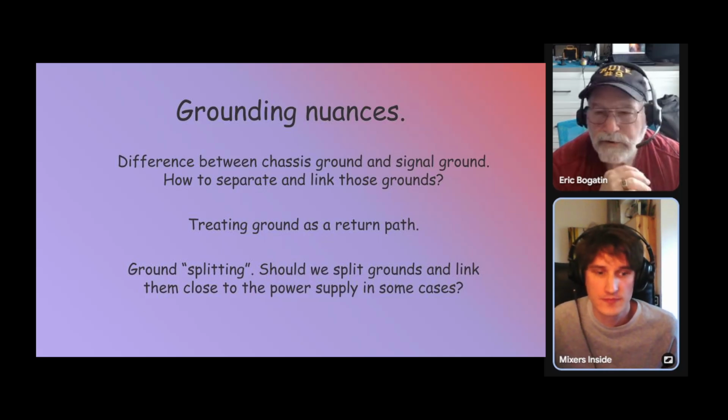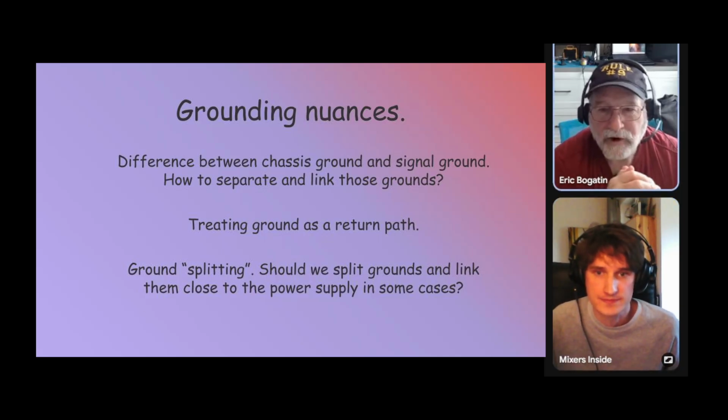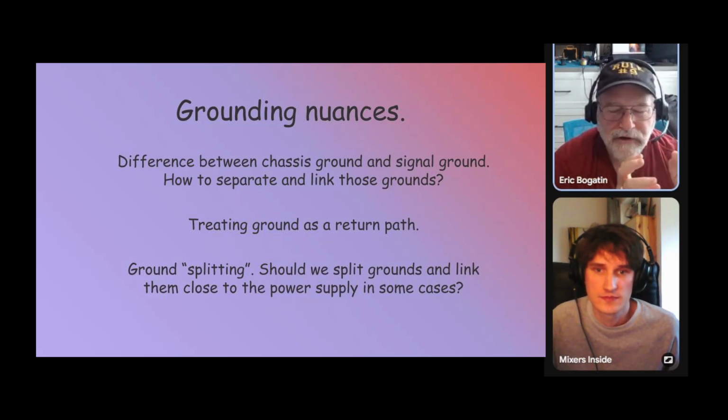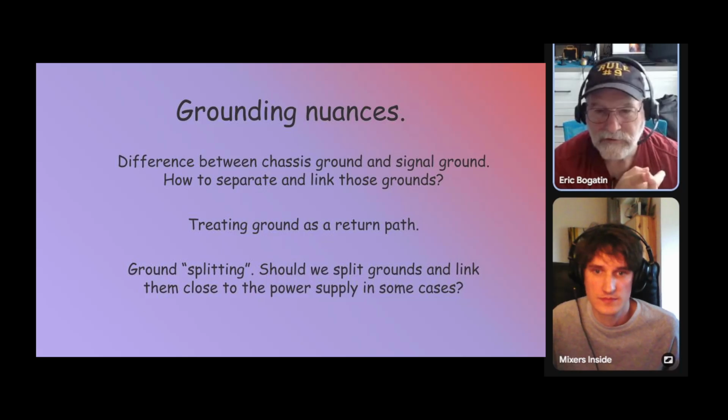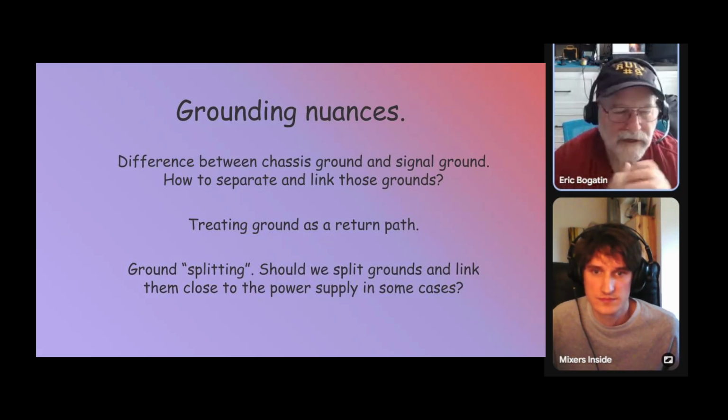Right. So ground is a really confusing topic, and part of the reason is because of the words that we use. So there are 5 different kinds of grounds. Each of them are a little different, and you have to pay attention to them. The first is earth ground, and that is literally connected into the floor and into the dirt, provides a reference for a whole building.